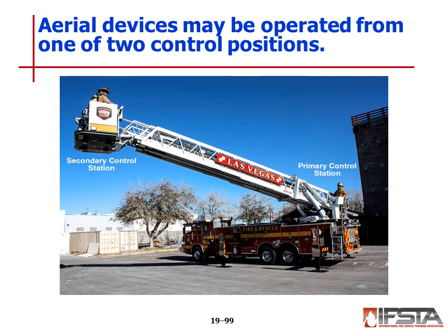In the secondary control position, either at the upper tip controls or on the platform in the basket, anytime there is a firefighter operating these controls, there must also be a trained and authorized aerial operator at the primary control position as well. The secondary control operator performs the final positioning of the aerial ladder during the rescue or other firefighting operations. These controls do not replace the lower controls as the primary position for the aerial ladder.